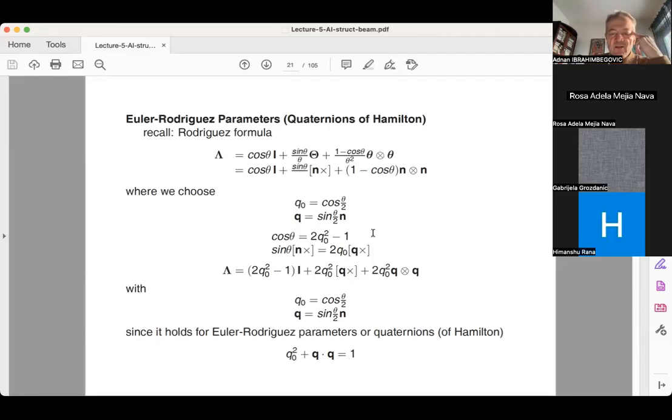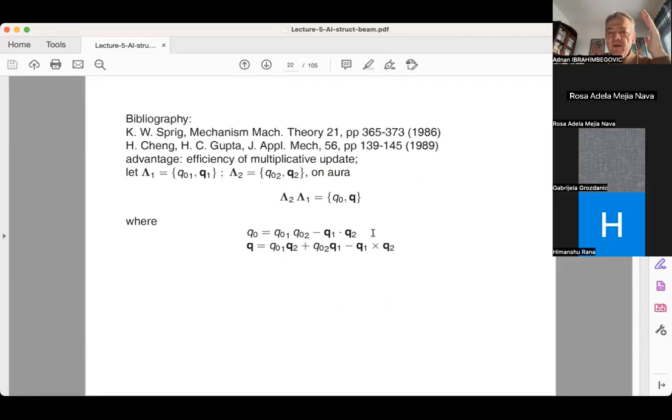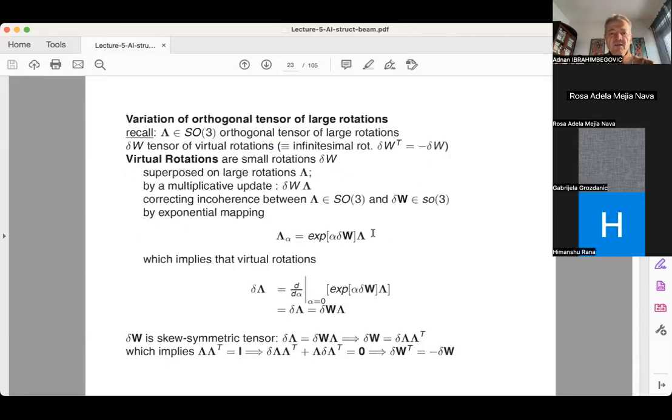or you can also use incremental rotation that we advocated, in which case you have the best benefits. That is, you have a symmetry with the tangent operator, and at the same time, with incremental rotation not being larger than 180 degrees, otherwise you cannot converge, you can certainly obtain quite good results.